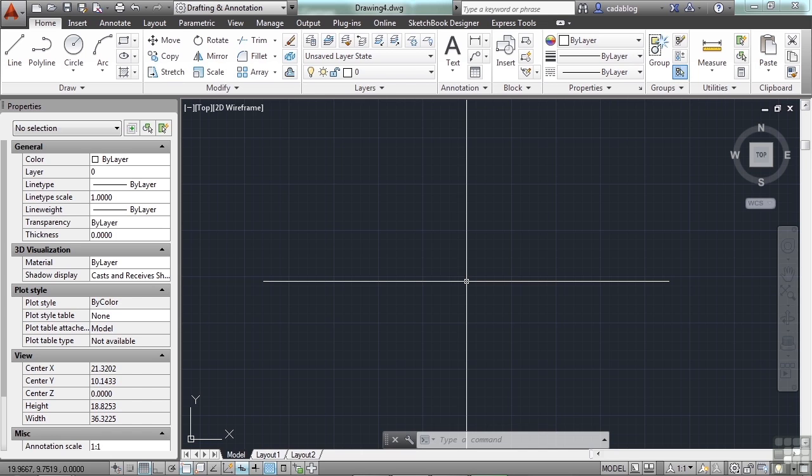And then now let's say, well, you know what? All those 36-inch doors, I want them to be 34-inch doors. You have to change them. So you have to delete them all, reinsert new. That's some extra work. But if you had a block in there for that door that was already a dynamic block, then you could design it so that it would fit all these needs, but with just one block. That would help you to make the changes very quickly. It also makes these blocks more useful since one block can fill many needs.